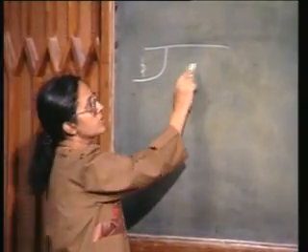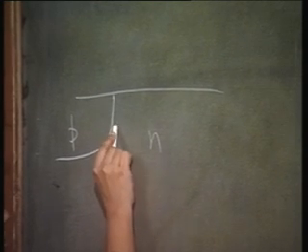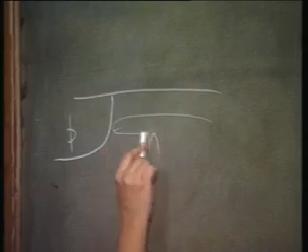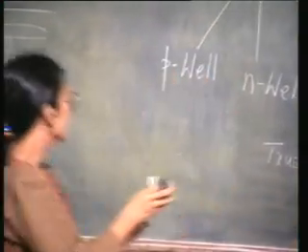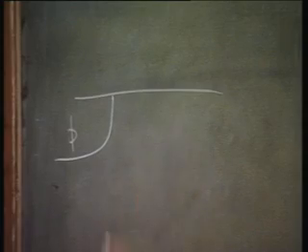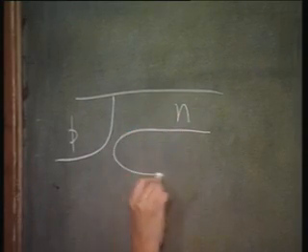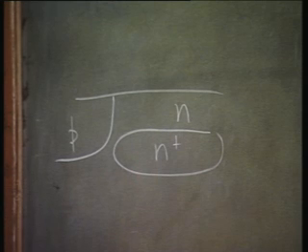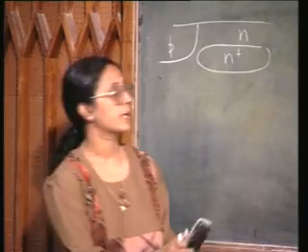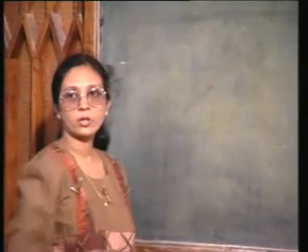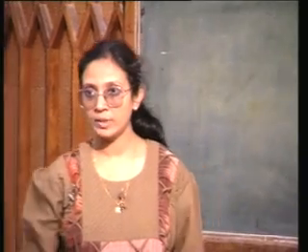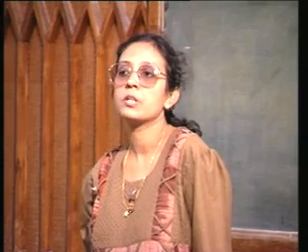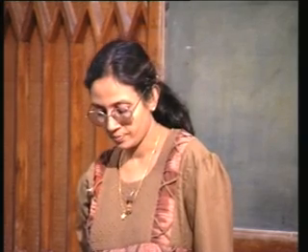Only thing what you are doing is, in this N-type substrate, somewhere deeper inside you have an N implantation to prevent punch through. So, this is the secondary P well. In the same manner, you can also have a secondary N well, in which case you basically have an N well, but in the P type substrate also you carry out a deep implantation to prevent punch through.